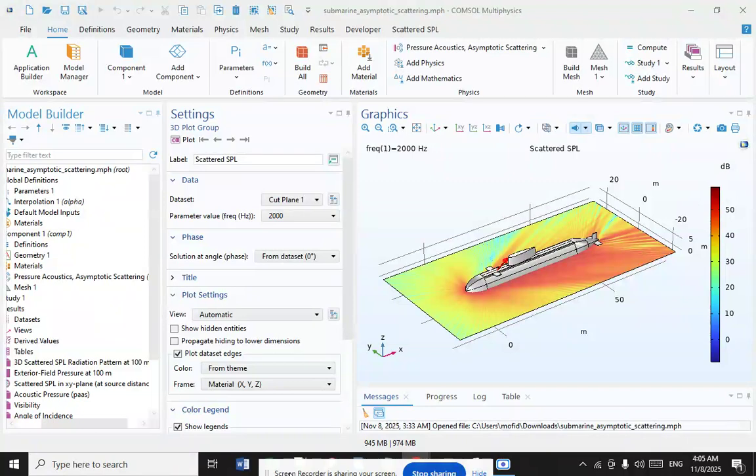The resulting eikonal equation for the phase and the recursive system of transport equations for the amplitudes are independent of frequency. The diffraction effects ignored in RM and GO are taken into account in refined approaches such as the uniform theory of diffraction and the geometrical theory of diffraction. While implementations based upon asymptotic methods are frequency independent and the accuracy increases with increasing frequency, they are not designed to converge for fixed frequencies.